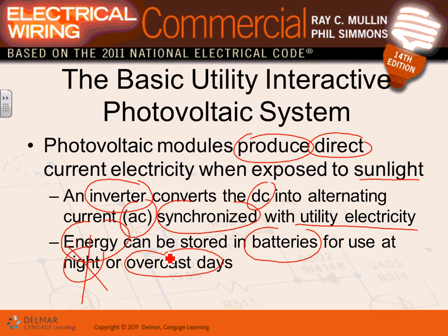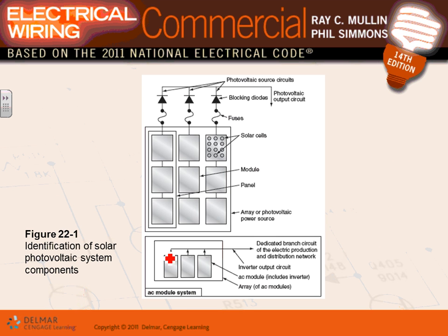If you are a standalone system, guys, there's no grid. You live in the boonies and there's no grid there. What they do is they have backup batteries. So you charge the batteries during the day, and you utilize these batteries at night. Any comments, guys? Any questions about utility interactive? But utility interactive, guys, typically works if the grid is there. If the grid is not there, it doesn't work.